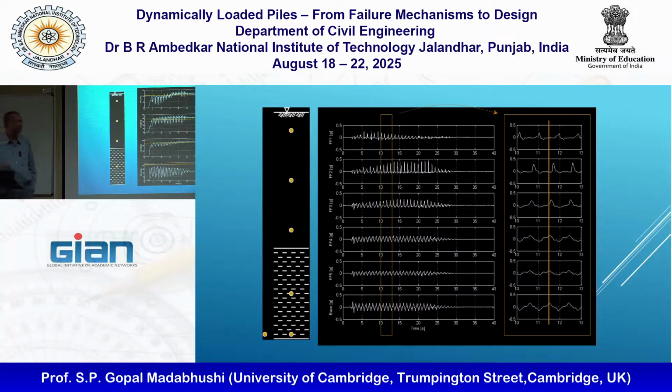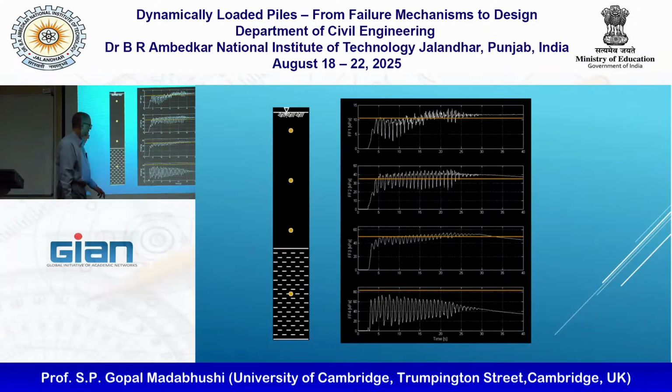Pore pressures. In the dense sand, I get maybe 60 kPa excess pore pressure. But if you work out to liquefy the soil, I need about 80. So this dense sand hasn't quite liquefied. As I go to the top, I can see I'm crossing the liquefaction line. So we know the shallow layers, the slope layers, are all liquefied.